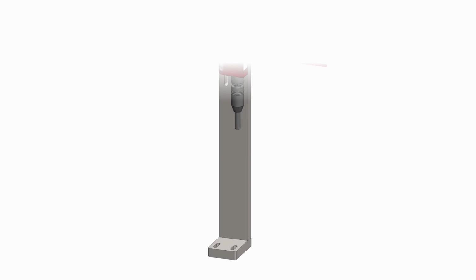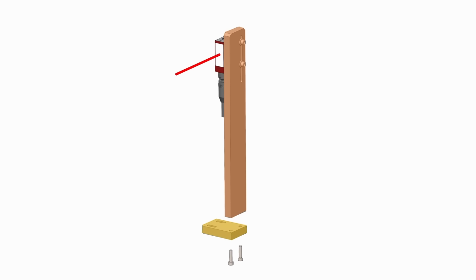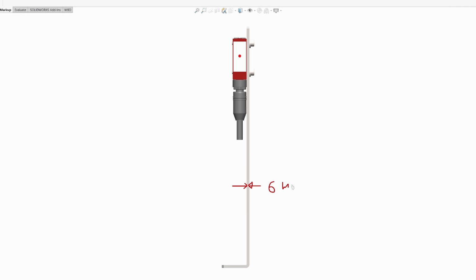So to solve this problem properly, you may need to shift to a machining process instead of the sheet metal process. But then you have to redesign the complete part, create multiple parts, all the boltings, and then assemble it with the bolts. And that's the real pain for any mechanical engineer because it becomes time consuming and very frustrating. And in real projects with deadlines, you rarely consider redesigning the part. So instead you start compromising, and it eventually leads to a poor design.